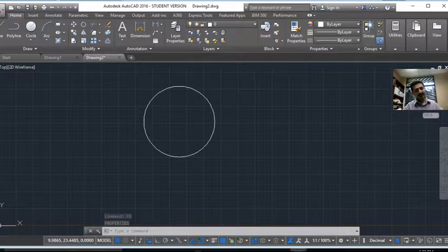I know, again, this is a lot, but those are important commands that we need to learn before we get going with drawing itself. Another very important tool or command that you need to learn before you start to draw is object snap, which we talked about a little bit, but now it's time to talk about it more. How can I activate that? If you hit F3 on your keyboard, you notice here in the command line, object snap off. If you click one more time, object snap on.